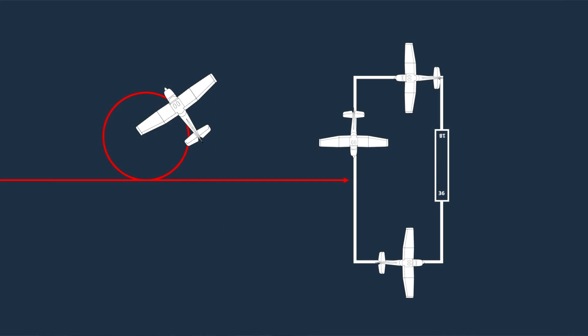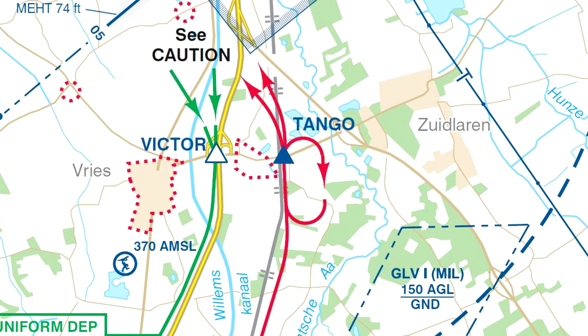As you can imagine, it can get quite busy in a VFR circuit, especially at uncontrolled airports. There's not really someone managing the traffic or instructing other traffic to halt before entering the circuit. So you have to be very wary of this, especially if you're flying into an uncontrolled airport and joining the circuit there. If you know it's very busy, one trick is to hold away from the aerodrome traffic zone and stay away from the airport until it seems a little less busy. And if you're flying into a controlled airport, the controller might tell you to hold above a specific visual waypoint, so keep in mind that it can happen.